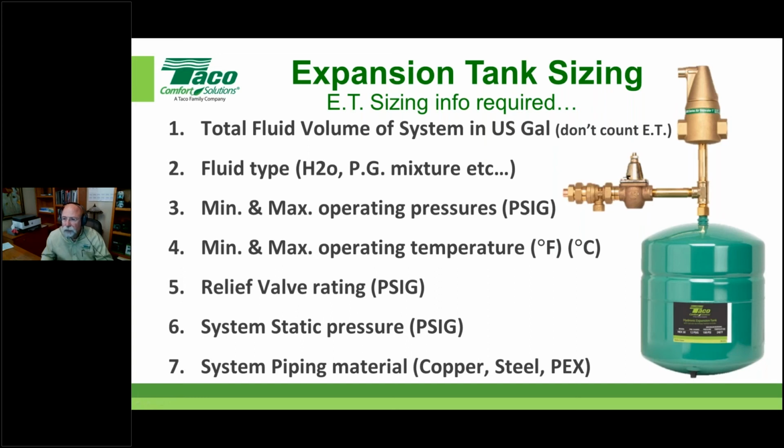I had a valve here, like this little check valve assembly that we give you with this kit. So I spun my tank off, checked the pressure, filled it, made sure it was back up to 15 pounds where I was running my particular system, and put it back on there, tightened it down. Forgot to open the valve, right?